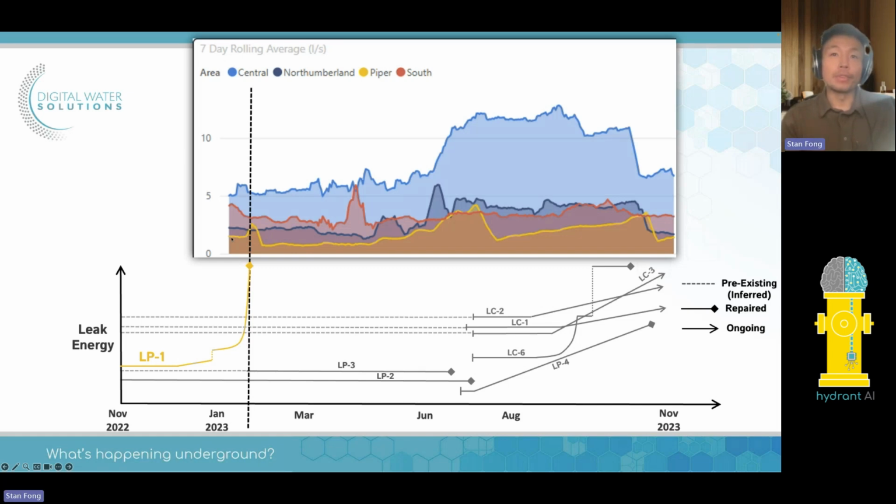So that's why it was important for the acoustic to come in and be able to pick that leak out early, make them aware of it, right? Once it hits this point, it's evident that it is indeed going to be a leak. It's going to be a break. It breaks, you do the repair. And now you can take this and quantify what that's worth, right? You can actually use this and compute how much water was lost, again knowing the pressure there, knowing the flows.